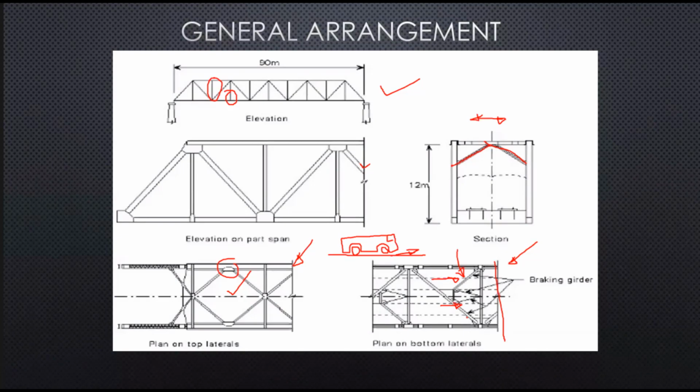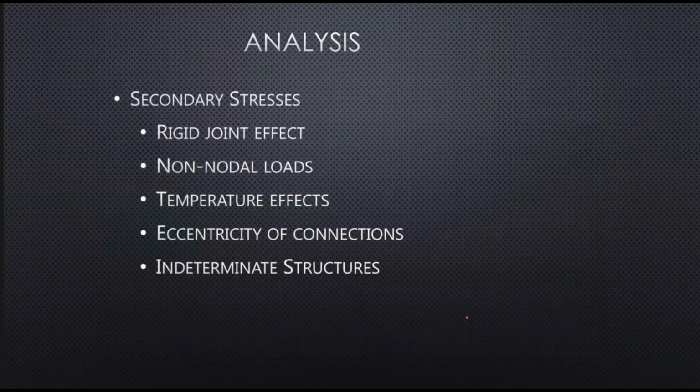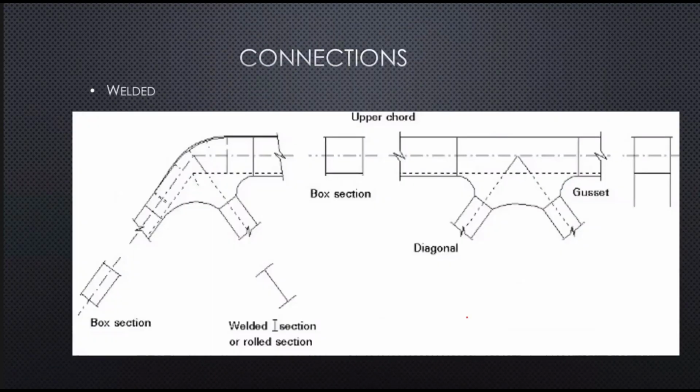Now, in the analysis, I should take the rigid joint effect. I used a plane frame, and if there are non-nodal forces, I need to account for them, because in all the trusses we say the nodes are loaded. We can, of course, in today's computer software, apply the loads in between. We need to take the temperature, eccentricity. This we have already seen.